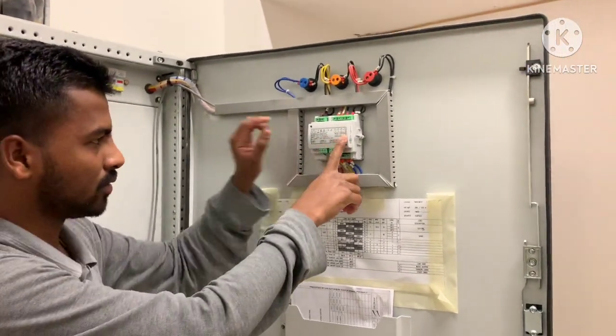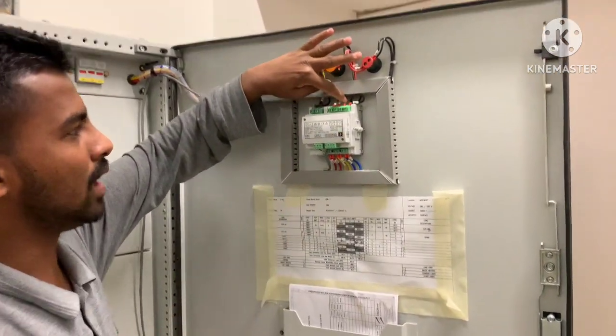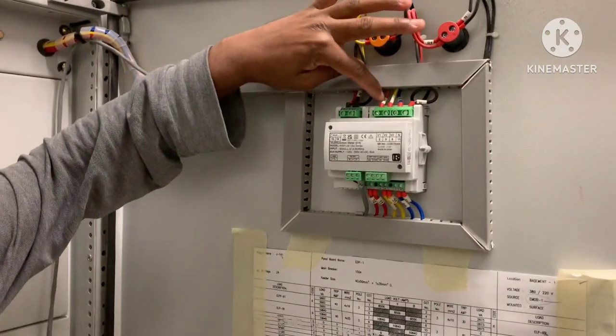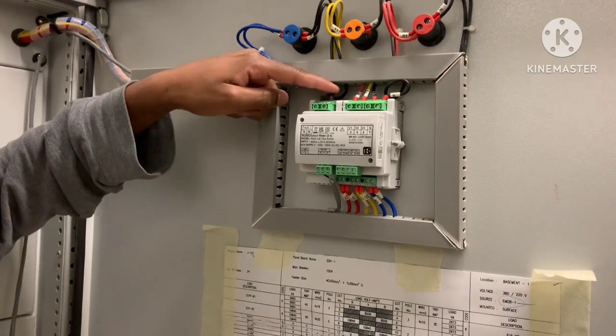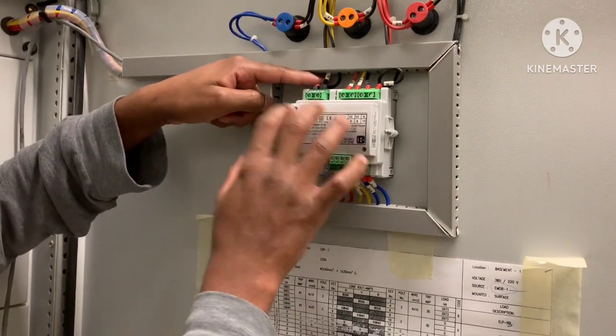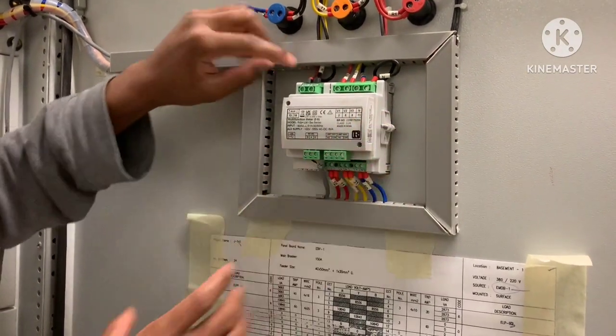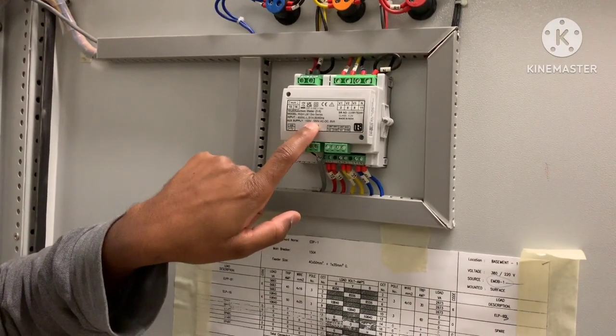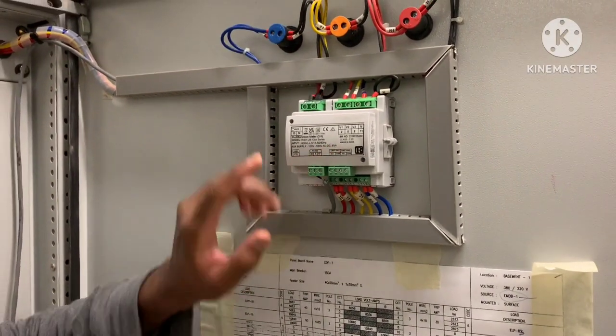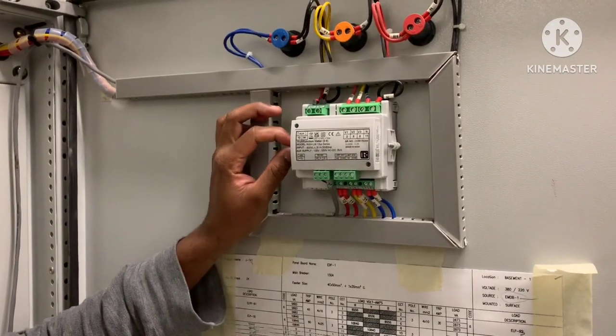there are some wires. These three wires are for the three phases R, Y, and B, and the fourth one is a neutral. Okay, the two are the power supply for this meter. So it's taking the power supply. Auxiliary power supply is from 100 volt to 550 volt AC or DC. You can provide it for the meter.